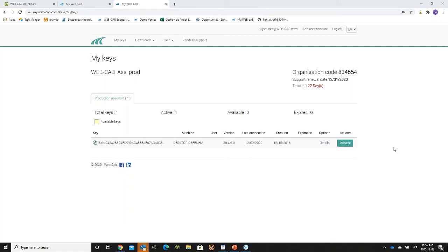And to respond to your question about rolling carts and fixed racks, that's a mentality in the factory, depending on whether you want to go in that direction or not. But mostly, why some people are moving to fixed racks is that when you're moving with a mobile cart, you're actually moving in what we call silos. So you have to wait until everything is inside your rack, completed, to move it to the next working station. If I'm at the edge bander, I have to wait until everything is complete in my mobile cart, so normally your work order. And then when you have everything there, you have to move the rack to the next working station.